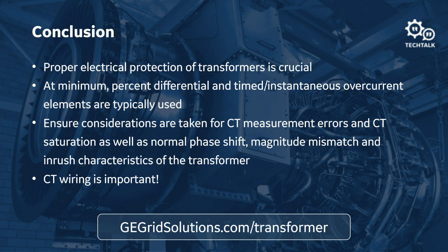All right, so here's an interesting question to start with, more on the basic side. Someone asked, why do transformers hum? The short answer to this is that the current flowing through a transformer, because it's alternating, produces a similar alternating magnetic effect on the iron core.